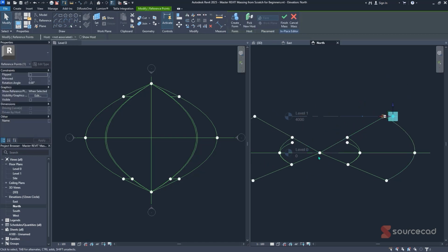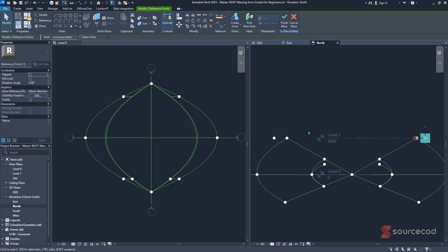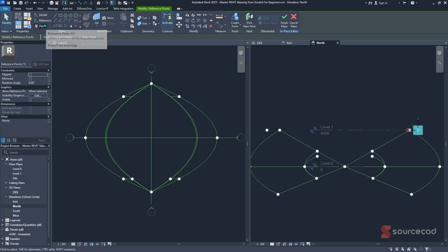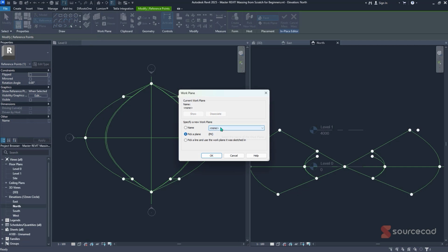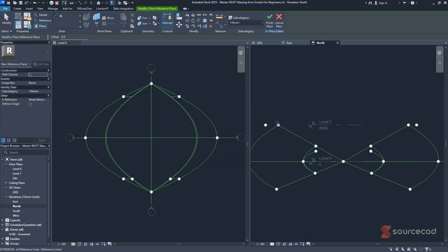And then we want a central point here. And to do that, we just need to have, let's say, a reference line. And to do that, you can just click on reference, and then I can create a new one actually. So let's click on plane. And all I have to do is, let's say, get to this center point. So I'll click that point, click on this to give it a code of RF for roof, then click on away. And then I'll just simply click on this specific point here. Or let's say I'll eyeball this area here and RF1.